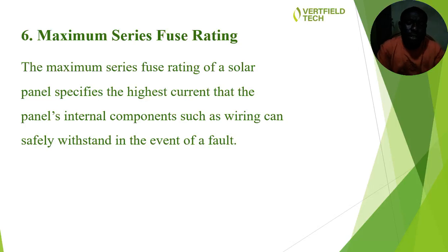Moving ahead, you have the technical parameter we call the maximum series fuse rating. This maximum series fuse rating specifies the highest current that the panel's internal components, such as wiring, can safely withstand in the event of a fault.